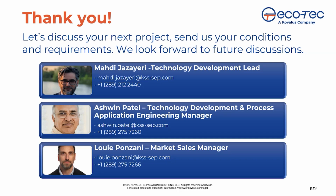Okay, Madi, our first question is with respect to resin life. What is the typical resin life for the DLE applications for your softener from Kinley Moore? Okay, that's a very good question. For our Recoflo softener, because we don't use harsh chemicals and the cycles are shorter, the resin life is up to 5 to 7 years, depending on the temperature. So we are looking at 5 years minimum of resin life.